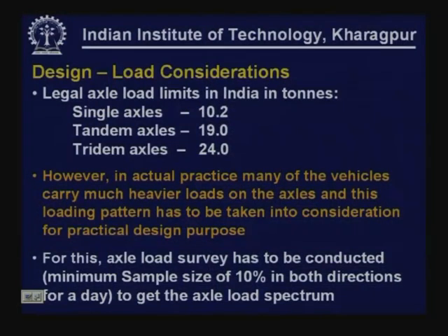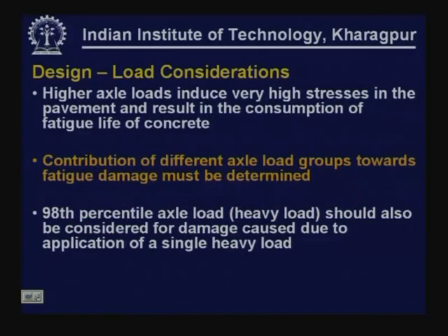Obviously, for this we have to conduct an axle load survey. A minimum sample size of 10% of the total vehicles in both the directions will have to be sampled to get a proper axle load spectrum. Higher axle loads induce very high stresses in the pavement and result in consumption of fatigue life of concrete. Contribution of different axle load groups towards fatigue damage must be determined. The 90th percentile axle load, which is considered to be a heavy load, should also be considered for damage caused due to application of a single heavy load.